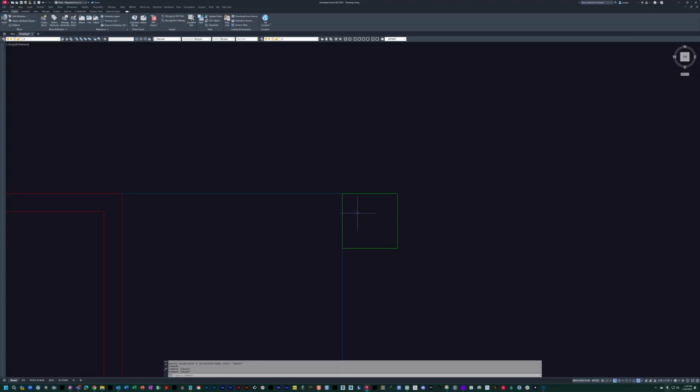Now, I'm currently drawing this in our green, which is our structure. I don't want a 12 by 12 structural column that then gets offset 2 inches to cloud it out with drywall or whatever, because then that becomes too big. So I'm going to offset this in 2 inches, which gives me an 8 by 8 interior column.